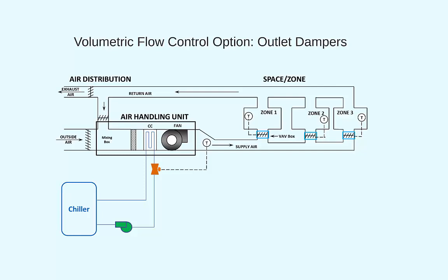However, the static pressure in the supply duct will increase, just like we saw in the hydronic systems when the valves closed. If we don't install some device to change the speed of the fan when the static pressure increases, the operating point of the system will just ride the fan curve. Let's illustrate this.